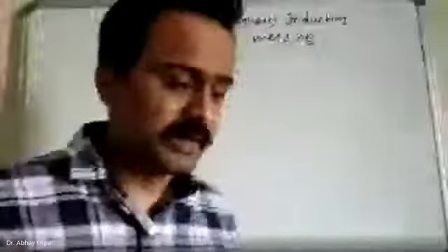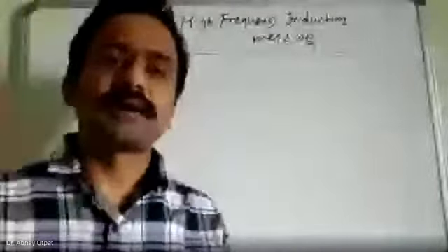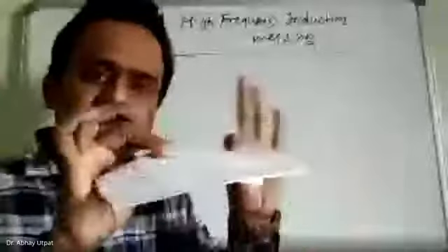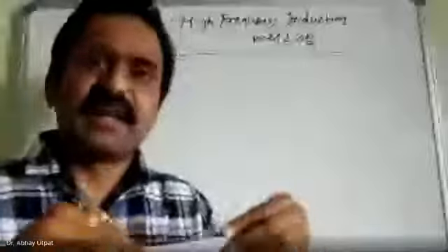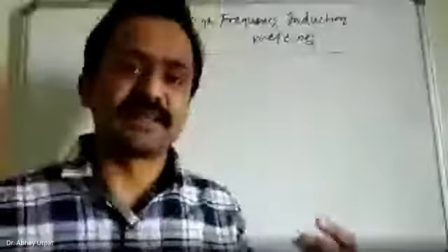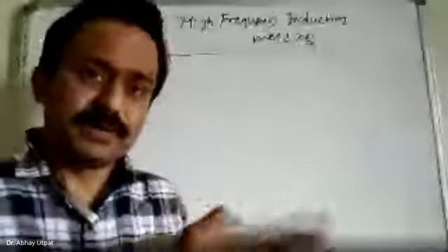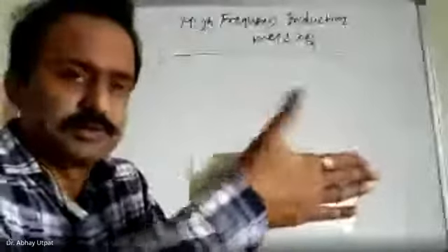Then what will I do? I will take this gasket. It is made up of the same thermoplastic as the base material, and assume that it has the same shape as my palm. So this is a thin plastic material having metallic particles in it. I will design the joint, giving shape to it as per the joint. And now I am keeping it in between in this way. Assume that this is of the same shape.